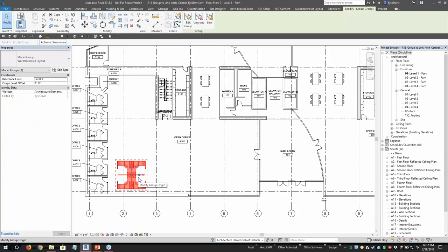So when you have a group in here, I just got another question. Why isn't the toilet following with this floor hosted? The toilet that I placed in my model is not floor hosted. It is level based, so it's not going to break when you move it. But if it is wall hosted, like a commercial toilet that's hung on the wall instead of on the ground, that toilet might have the same issue. But the toilet I had was not floor hosted. It is a free-floating, non-hosted toilet in my model.